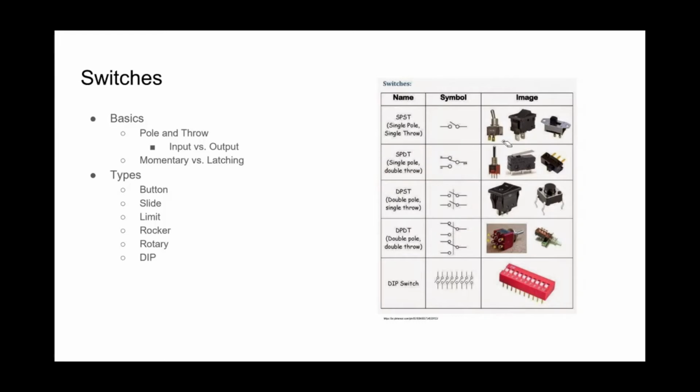You can kind of extrapolate this onto the other examples down below, like a double pole single throw has two outputs and only one option for each output. So that's a double pole single throw because those are connected with the same switch. Or we have a double pole double throw. So two outputs. Let's erase those errors so it's less confusing. Two outputs, and each of those outputs has two options to select from. Again, that would be a double pole, double throw.